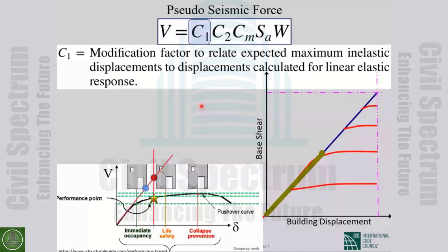Very nice. If you apply the load elastically, you get this distribution. If you reduce the strength, for example, you use a small R value, and the building gets damaged, but the maximum displacement is almost this. Even more interesting, you reduce the strength of the building further, the building is so weak now, but the maximum displacement is almost the same.